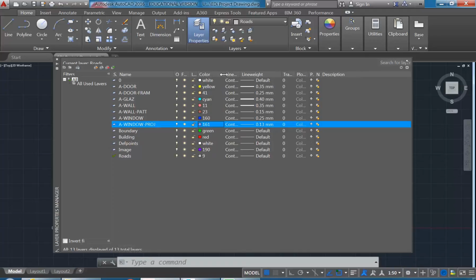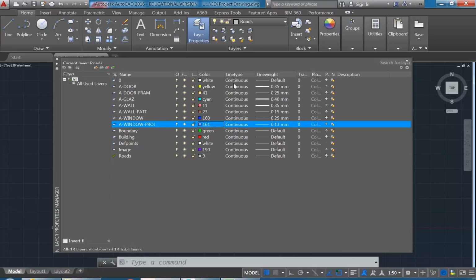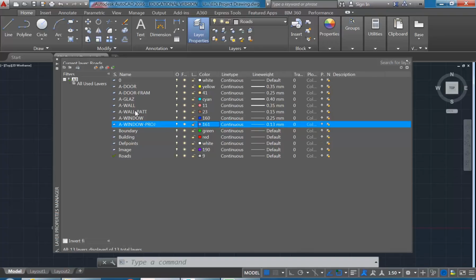Okay, so again, you can see I'm using a bit of guesswork to set the colours. If you're wondering, I do have templates with all of those layers made and a lot more, and I'll show you maybe some of them after I finish recording. And I do have pretty standard colours for all these things. You can see I'm following a system, but there are no real fixed rules required for setting colours. It's even looser than line weights because it's only going to be visible for you on the screen. You're going to print everything black and white, except for maybe the odd colour here and there. And so it's just a visual cue for you to see which layer an object's on.